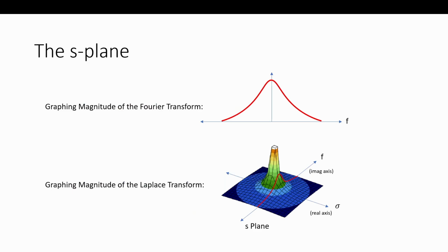So this is the s plane. If I graph the magnitude of that result, so that's us going to each one of these possible s's and seeing what we get, the results will have both magnitude and phase. You're not seeing phase here, but phase is also very important, so you're just seeing the magnitude. Imagine if I had this particular function, and if we restrict s to be the imaginary axis, then it's e to the j omega.